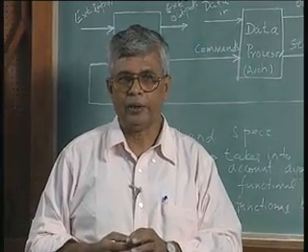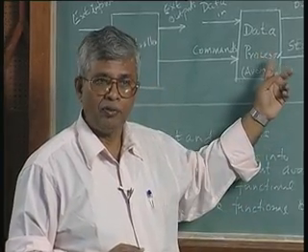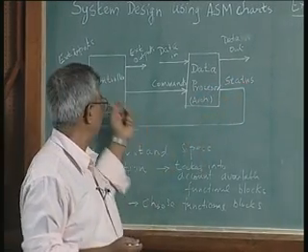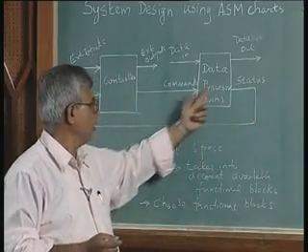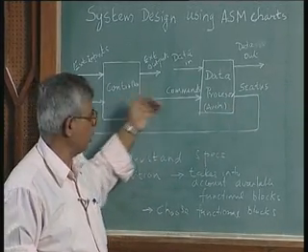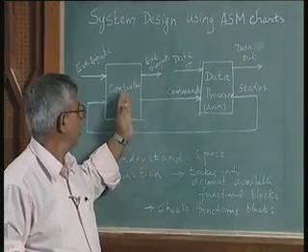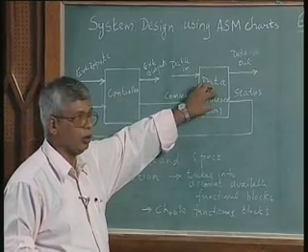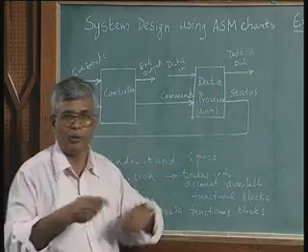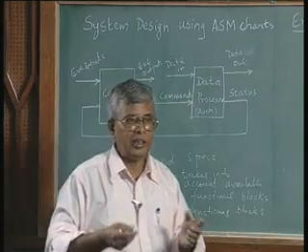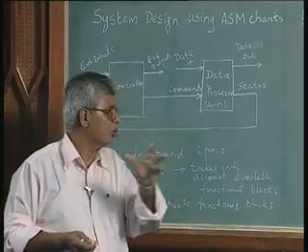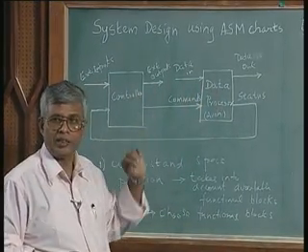So I have 2 ways of doing it. I can keep count of the shifts in the controller. Every time the status signal says 1 shift, I can take the signal in the controller, update the controller and issue the next signal. So I keep the counter inside the controller. On the other hand, I can put the counter inside the data processor and say when 8 is reached, only then I will give the status complete, otherwise it will keep on shifting and adding. So this is one example of how I can flexibly use the data processor or the controller for this job.